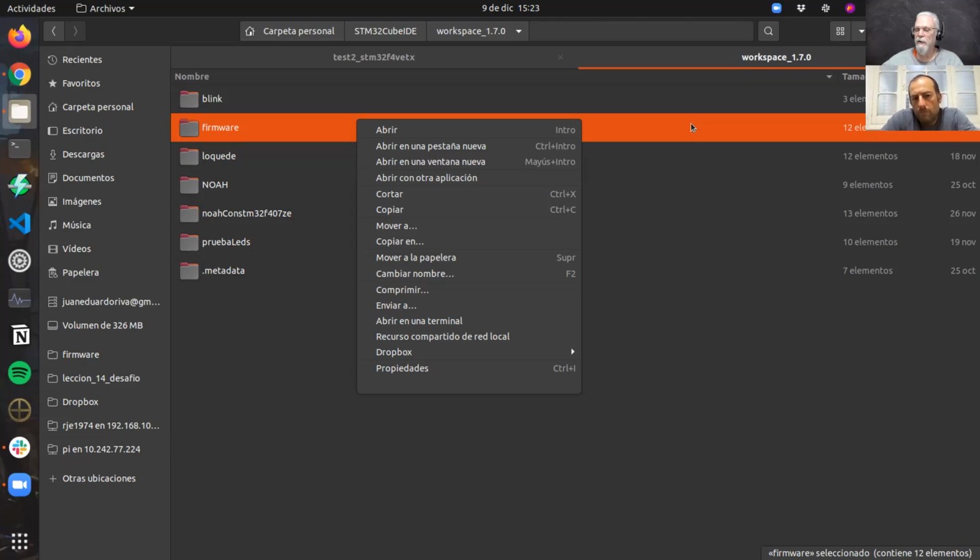Now, I don't know if it matters. It may be no different than running it externally, but that way there's less confusion, because you just start the one program and everything's accessed from the same spot. It could be it would complain if the IDE is open and the MX is open, and I'm not sure what's going on, but I would say if possible, don't run the Cube MX directly, and just always run the IDE, since that seems to be the way they want you to do it.